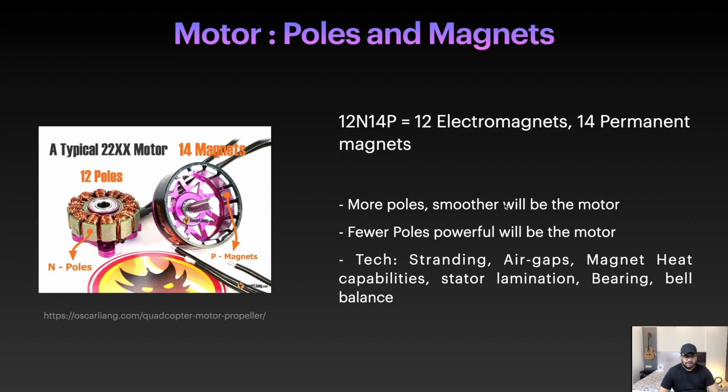What I mean by all these things is manufacturers need to keep in mind to give you the best motor out of their offerings. But we do not need to worry that much about it. We just need to worry about the width, the height, maybe the number of poles and magnets. These things we should leave to the manufacturer. But it is good to know that the air gaps, what magnets they are using, and what lamination they are using all affect the motor performance.